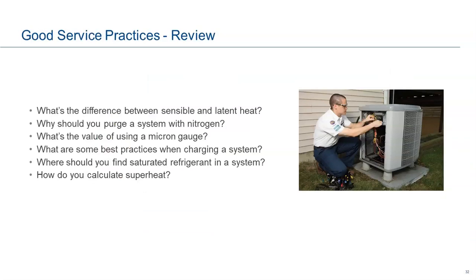Latent, we can't, okay? We're boiling that water, but it's not changing temperature. We have a temperature probe in that water, and it just keeps staying at 212. When that last droplet of water leaves the pan on my stove, no matter how high I kick it up there, as long as there's water in there, it stays at 212. The second that droplet leaves and goes to a vapor, it goes to 213, okay?